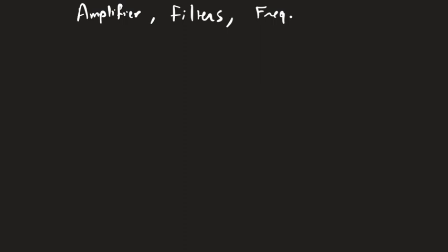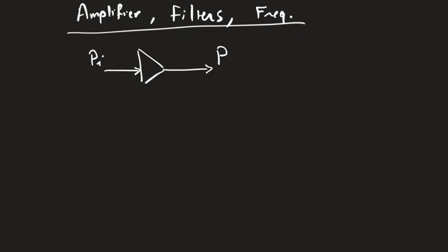There is a certain operating frequency. Outside that, you lose. Anyways, okay. So amplifiers, very simple. An amplifier is a piece of electronics. I don't care what's inside at this stage, right? You have some signal with input power Pi, and you get the same signal, so it's not distorted, with output power P output, and there is a gain. The relation says P output is equal to the gain multiplied by P input. That's what an amplifier is doing, right?